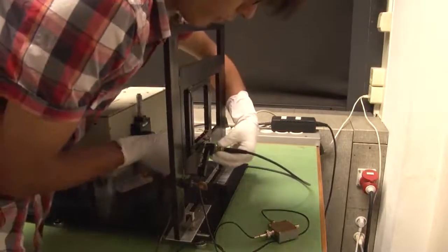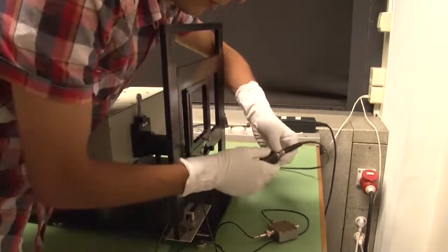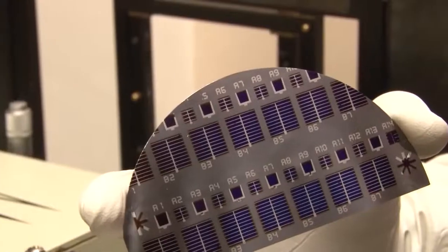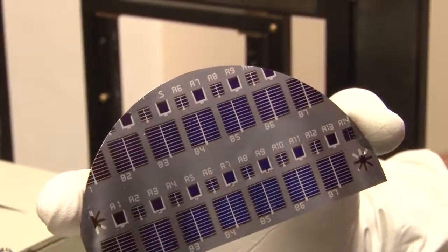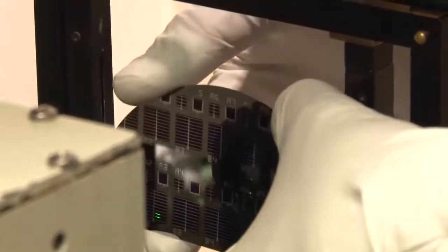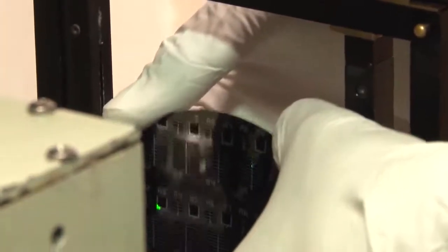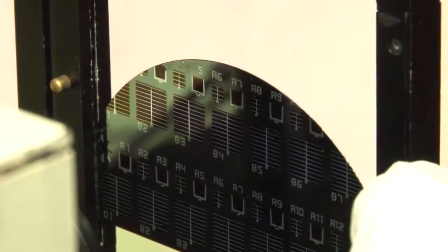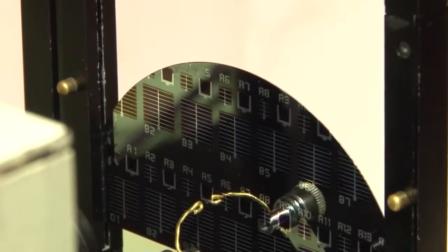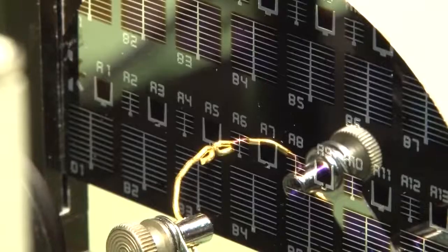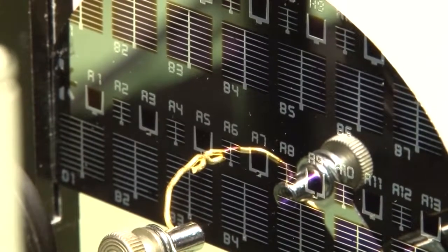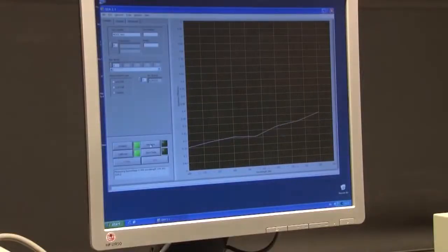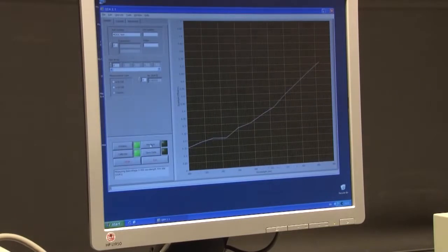After calibration of the spectral power density function of the light source, we repeat the same measurement with a solar cell. As example, we use a crystalline silicon wafer-based lab-scale heterojunction solar cell, which will be discussed next week. The solar cell is positioned at the same spot as the calibration photodiode. The contacts are connected to the ampere meter to measure the generated current. In this example, we measure the cell under short circuit condition. It means that no additional voltage bias is applied to the solar cell.